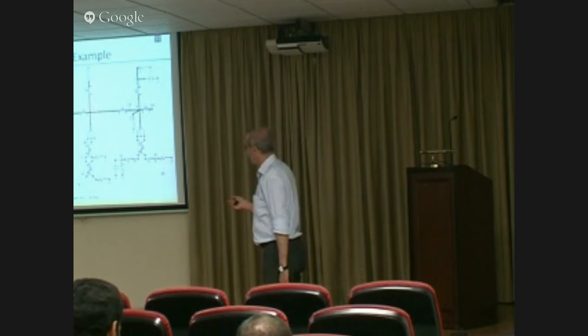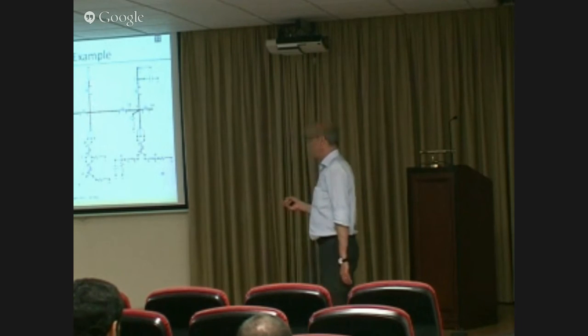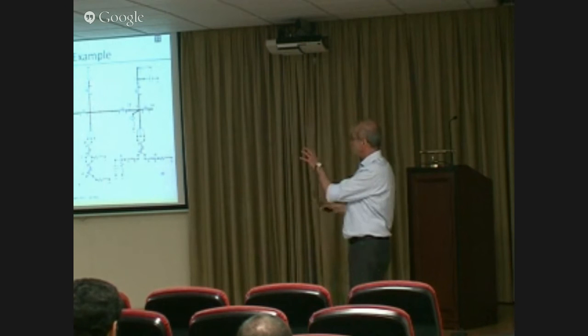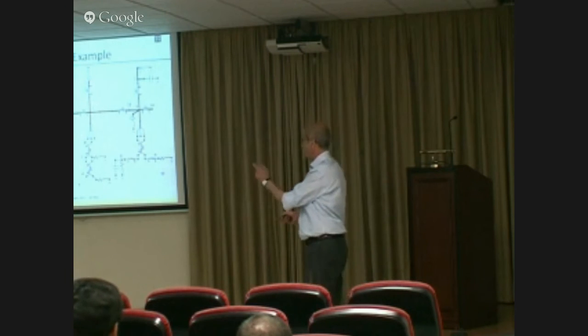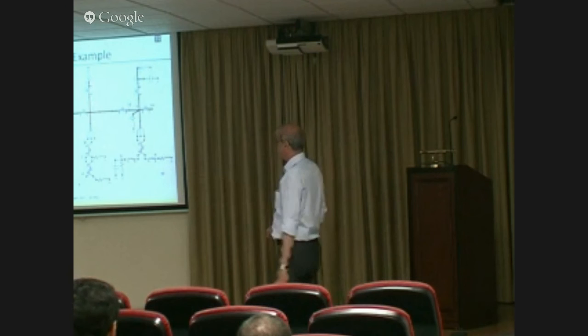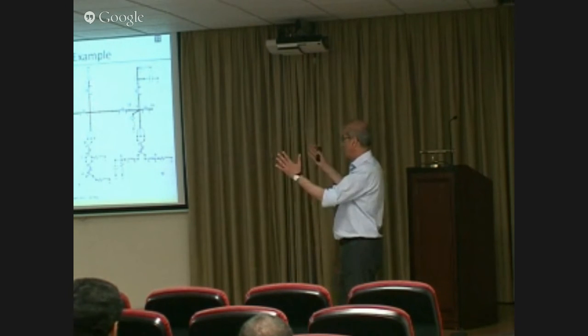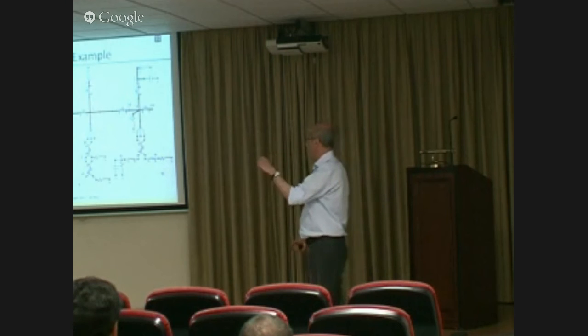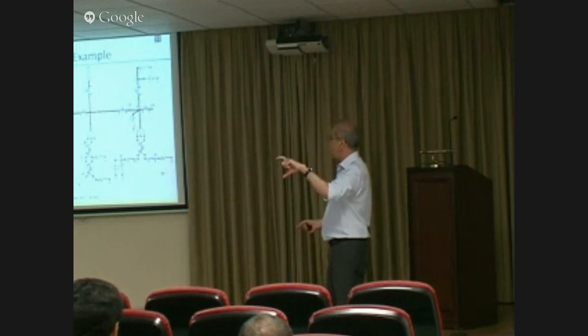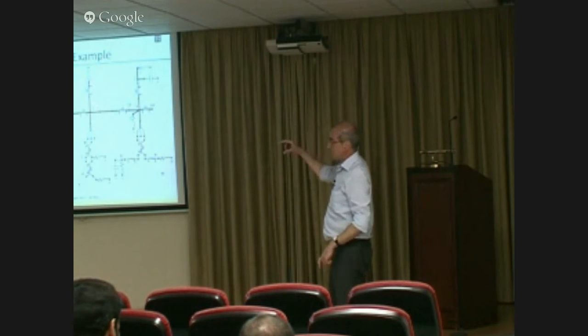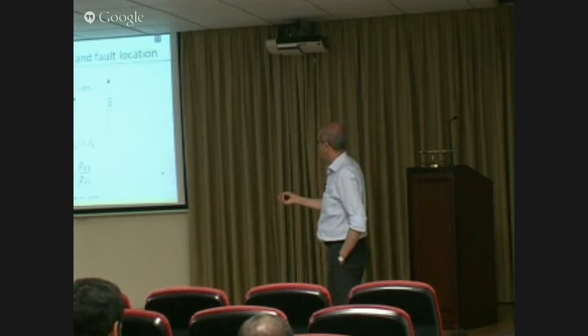If you want to model this as a pair of injections, obviously it's a three-phase system, so you will need two injections in phase A and B on one end, and then two injections at phase A and B at the other end, so that the equivalence that we talked about here will work.